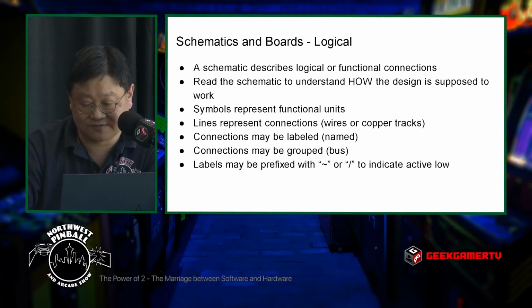The most common thing you'll see is the reset signal is active low, and often the name reset with the horizontal bar over it is what you'll see. That means that when the line is low, reset is active. When the line is high, reset is not. The processor comes out of a reset.